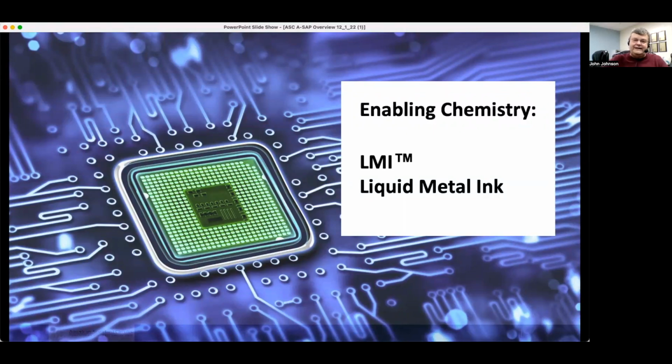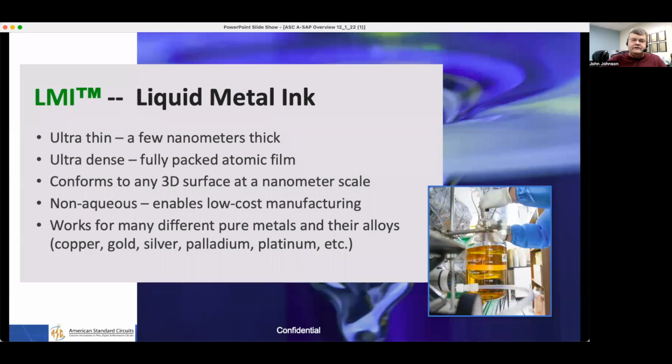And that palladium is a very dense coating of palladium, basically atoms touching atoms, and it's several levels deep of atoms, and so a few nanometers thick in actuality. And that density really helps in getting a plating down into all the small crevices and small vias that need to be plated.